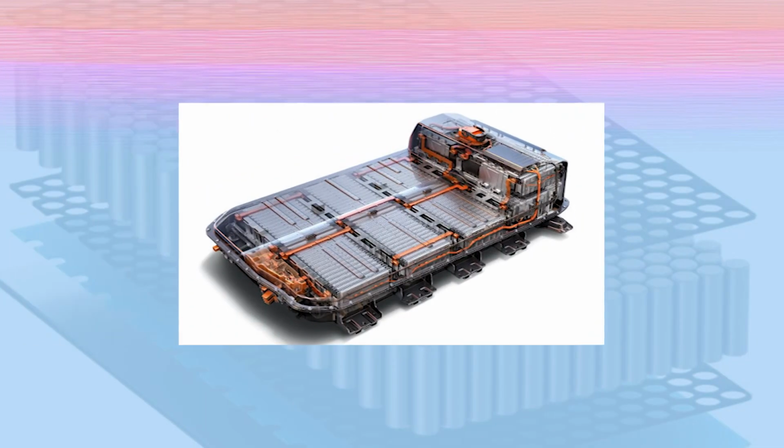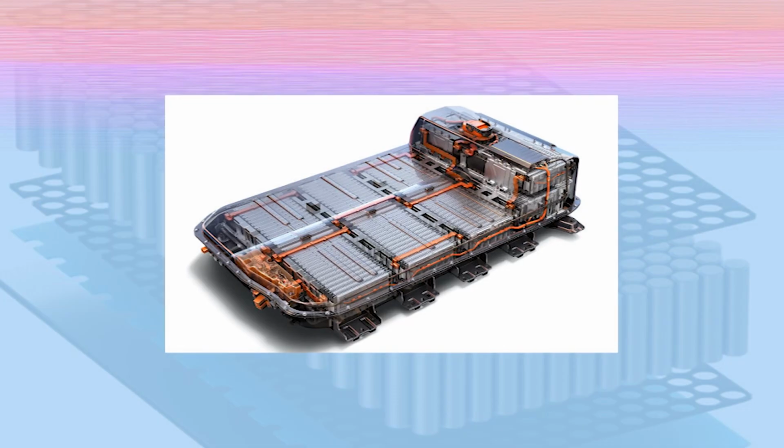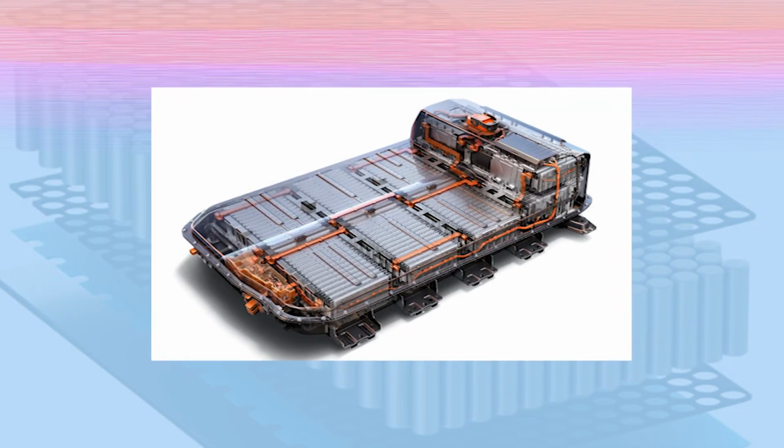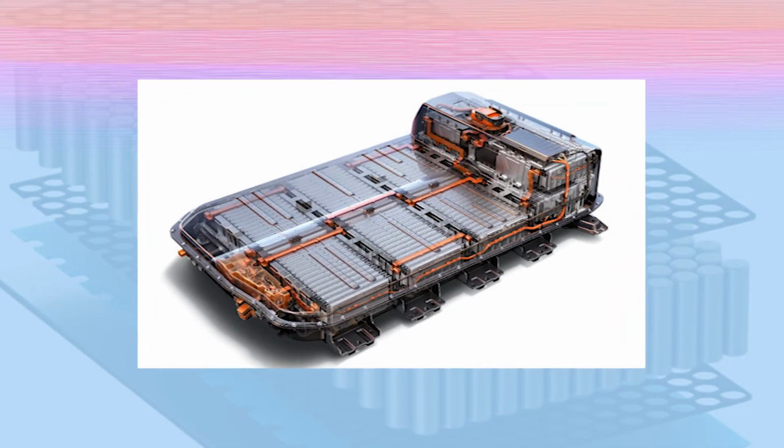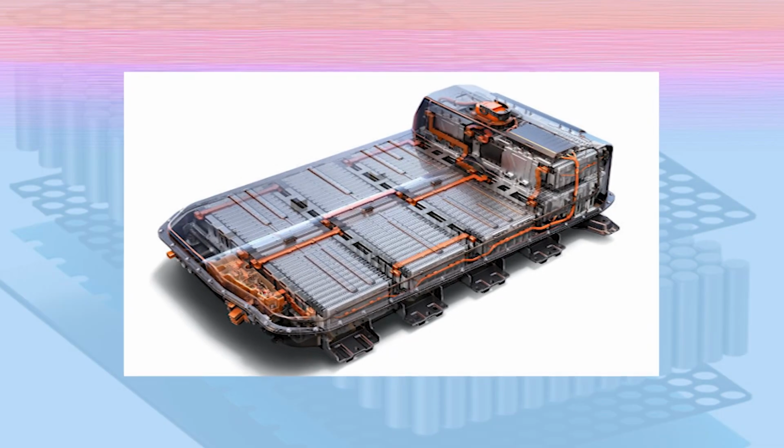Especially in heat sink and liquid cooling, space is the major constraint. So, before we design the thermal management system, it is important to know what amount of space is available in the vehicle, such that the battery is fitted, the thermal management of the battery is taken care of, and the thermal management for the power electronics is also taken care of in very little space.